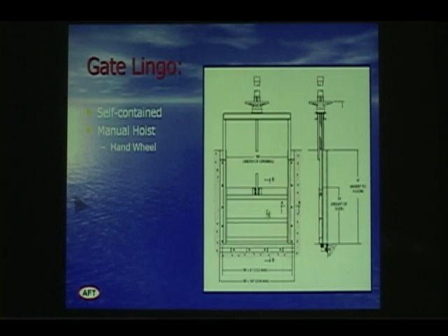So what you have is the gate down below here, you have a frame, you have a yoke assembly. This all comes in off the truck. The stem typically is installed, the actuator is typically installed. So the contractor is going to take it off the truck, lower it in, anchor it, install it with grout, whatever needs to be done, and he's done. Very straightforward. This particular one is showing a little manual hoist up at the top.